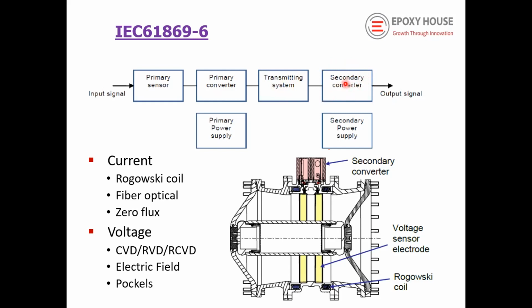There, this merging unit is sharing this to a relay or any other measurement device anywhere. So for the relay operation or anything, it can be given. So this is the general block. The converter can be separately powered. In the olden days, the same power was used, but nowadays it can be battery operated. This energy can be given separately.